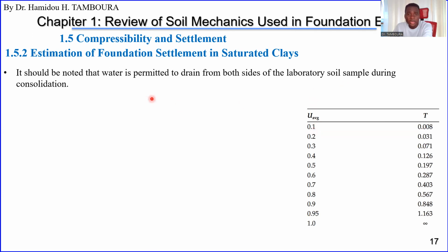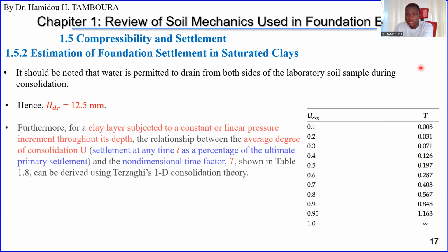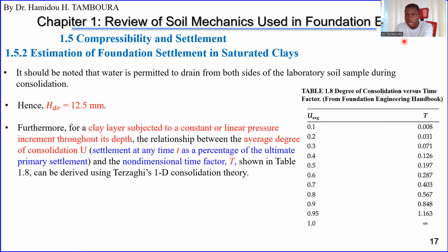And as I said, the H in this formula is 12.5 millimeter, because the water is allowed to drain from all sides, the longest path of drainage of water.